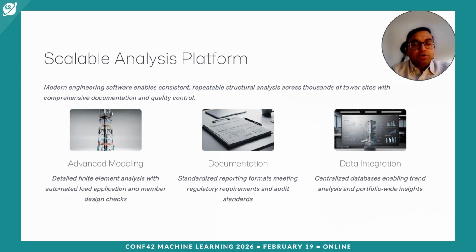Modern structural analysis software such as STAAD, RISA Tower, and tnxTower has significantly advanced our ability to perform detailed finite element analysis on tower structures. These platforms automate the application of hundreds of load combinations required by TIA 222 and ASCE 7 and perform member design checks against AISC 360 capacity equations. This alone has dramatically reduced analysis turnaround time compared to hand calculations.